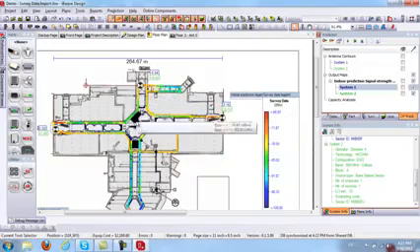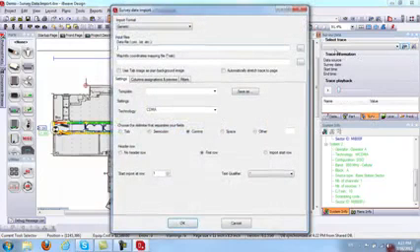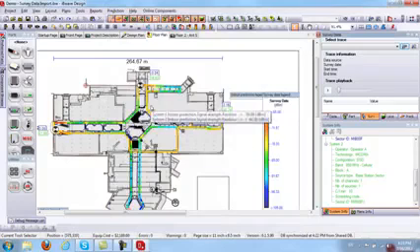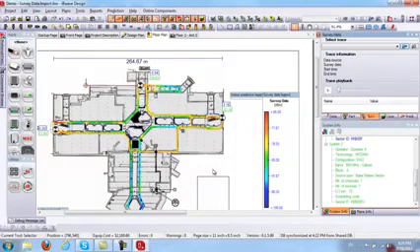So to import your measurements, you simply go to your survey data tab. You click on the plus sign here, and here you can import your .csv and map info coordinates, that tab file. And once you do that, you click OK. Automatically, your measurements will be displayed on iBwave design. There are a number of tools that we support the import from, like TIMS, Nemo, SwissQual, and so on. A list of them.